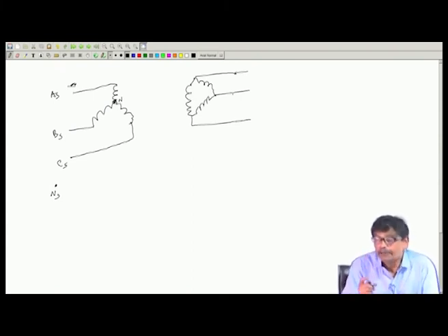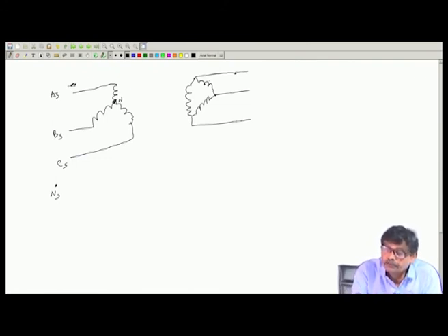But what happens is, it is a delta winding. There will be induced voltage, third harmonic component only I am telling, fundamental is there, they will sum up to 0 and there will be no circulating current. But so far as the third harmonic induced voltage is concerned in these 3 coils, they are cophasal, is not? And they find a closed path. So, in this delta